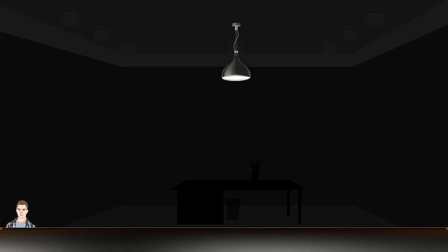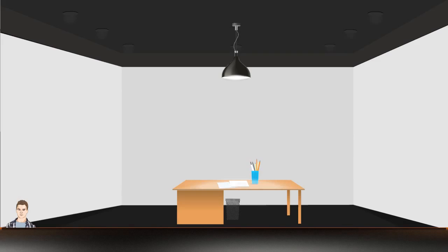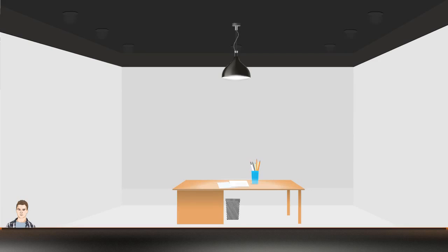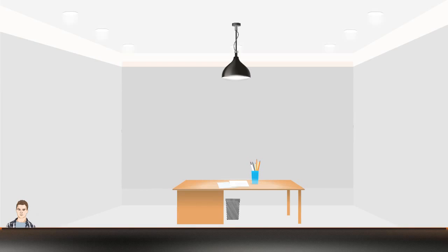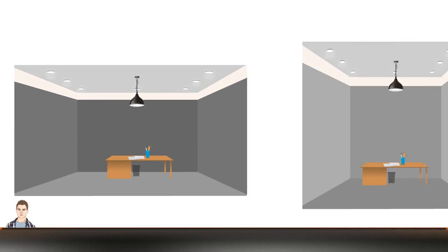For example, if the room surface is black, reflectance will be 0. For a room with white walls, the reflectance will be 100% and will vary equally when all the surfaces have been changed to white. The numbers are just typical and will vary from scheme to scheme, but you can see how much reflectance influences the final lighting level.